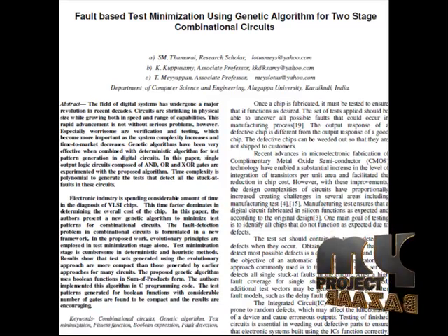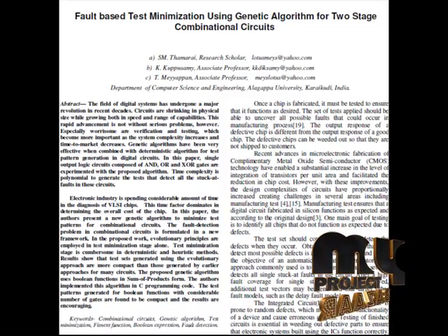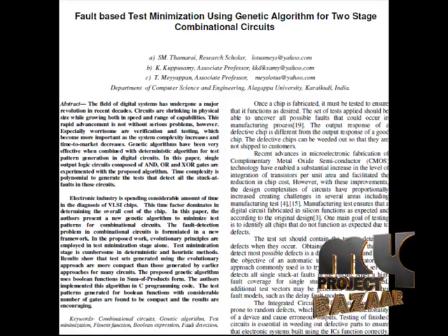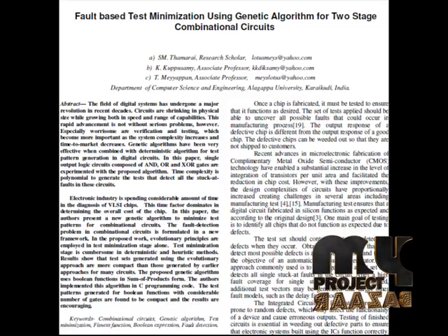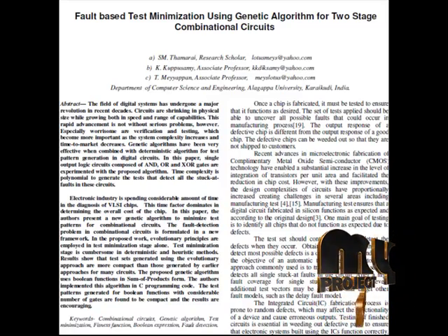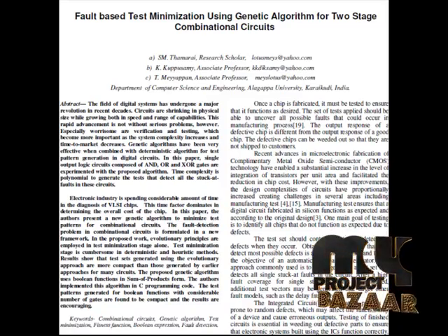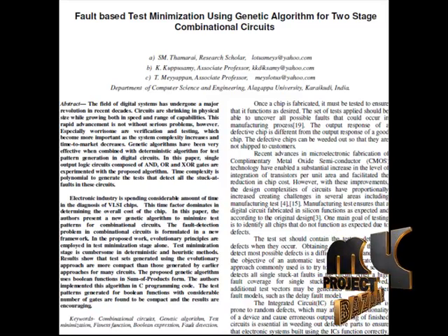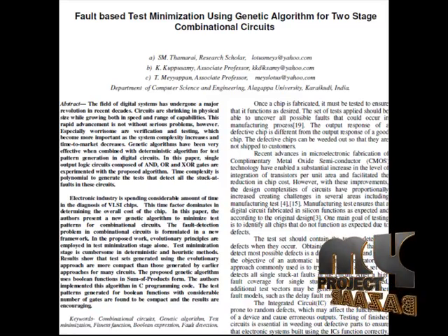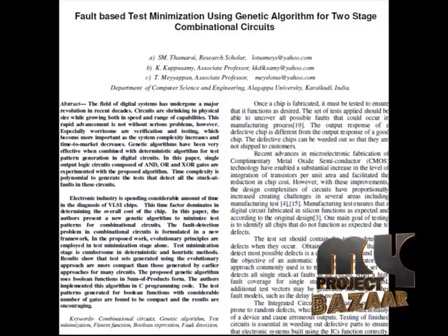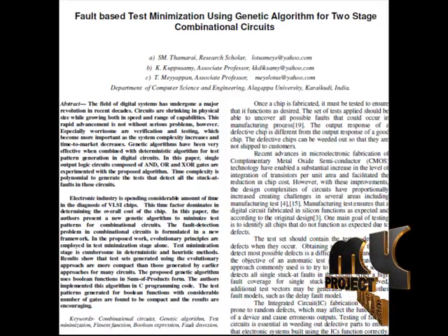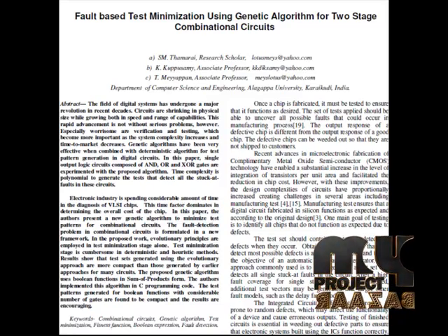The most popular fault model used in practice is the single stuck-at fault model. In this model, one of the signal lines in a circuit is assumed to be stuck at a fixed logic value regardless of what inputs are supplied to the circuit. Hence, if a circuit has n signal lines, there are potentially 2n stuck-at faults defined on the circuit, of which some can be viewed as being equal to others. The stuck-at fault model is a logical fault model because no delay information is associated with the fault definitions.